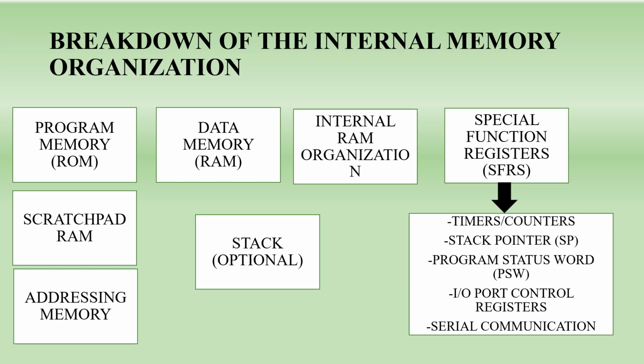Then moving on to the next thing, scratchpad RAM. It is going to occupy the upper address range, not from 00 but from 20H to 7F. So that address range it will occupy, and it is going to provide general purpose data storage.